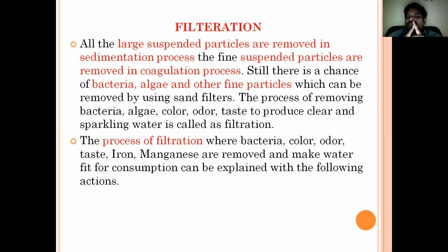Why do we need filtration? To remove the bacteria, algae, and odor. I mean odor in the sense of bad odor. Even the extra elements, when they cross the permissible levels, like iron and manganese, must be removed, or any other impurities or toxic materials also must be removed. See, iron and manganese are required elements in water, but when they cross the permissible levels, they must be removed. Understand? That is why filtration is needed.